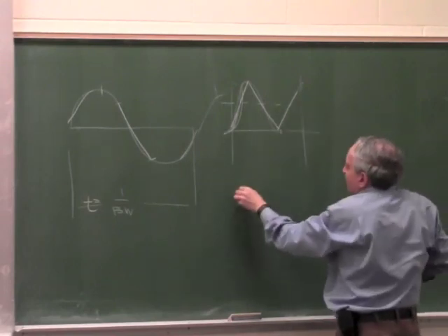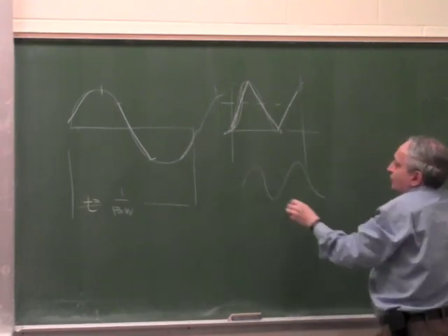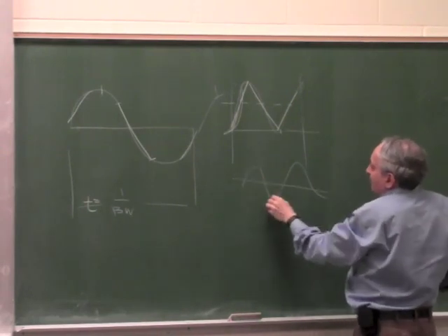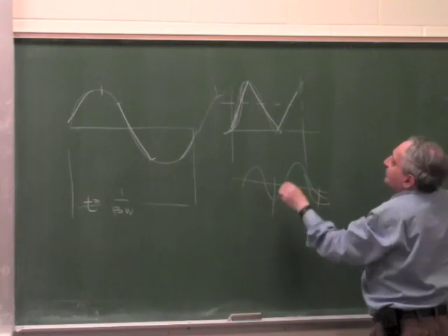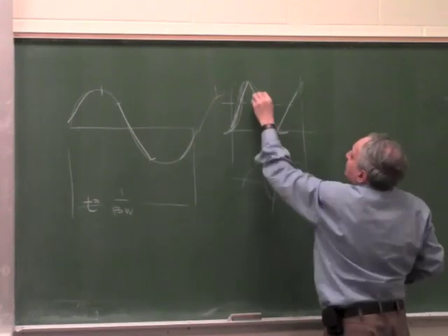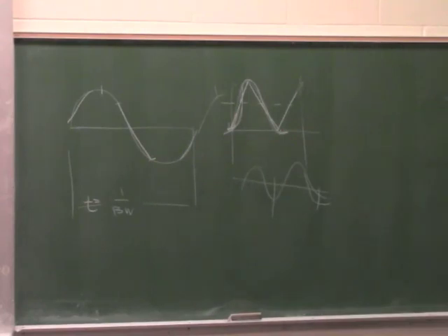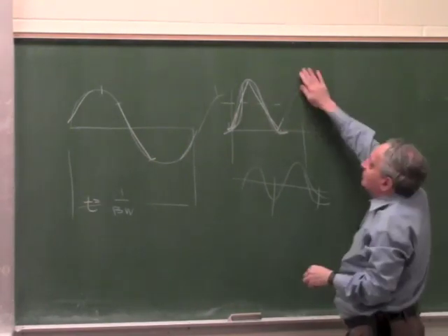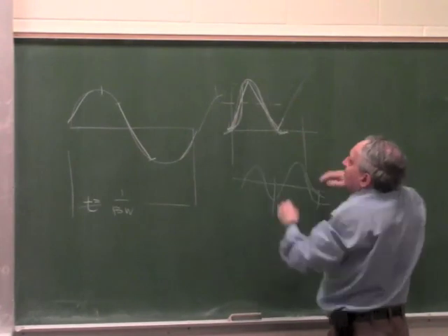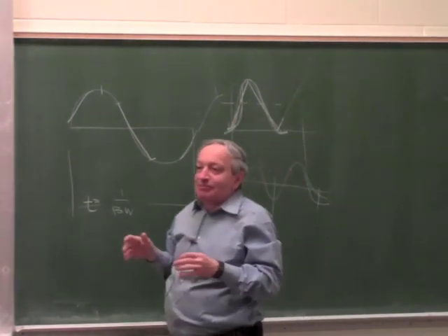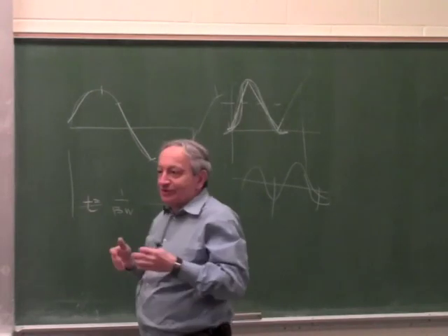that's not accurate, because if I take the sine wave and shift it above 0, let's say I can go from here to here. I can only go up to here. This is a sine wave above 0. So you can see it contains at least twice the rise time, and actually more. So that's just to show you that the rise time is much faster than 1 over bandwidth.